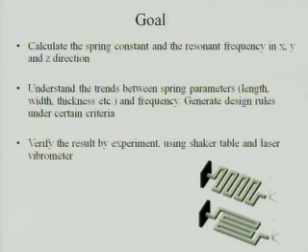My research goal is to calculate the spring constant and the resonant frequency in x, y, z direction, to understand the relationship between the spring parameters like the length, width, and thickness, and the frequency, in order to generate the design rules. Third is to verify the results by experiment. So I'm using a shaker table and laser vibrometer.